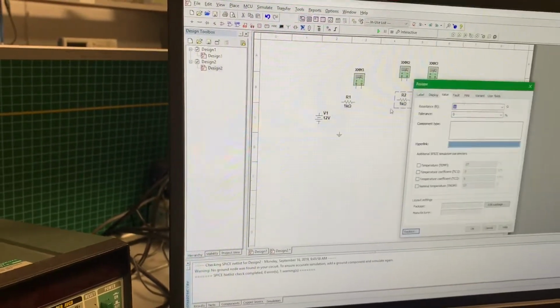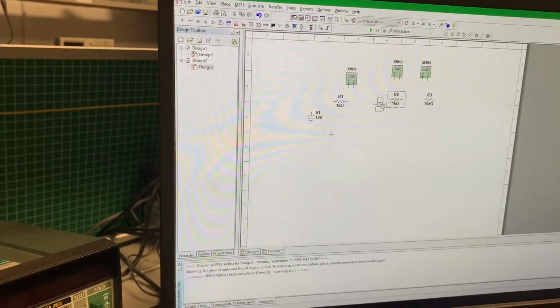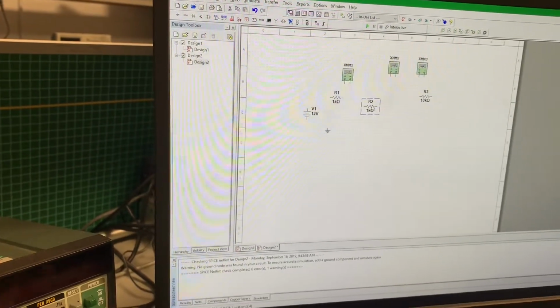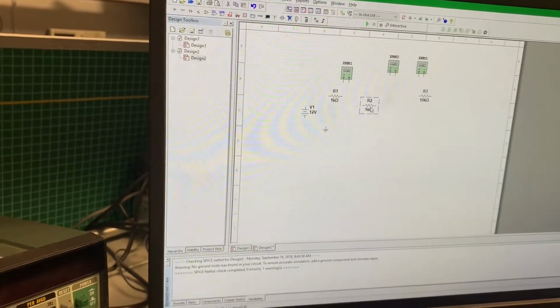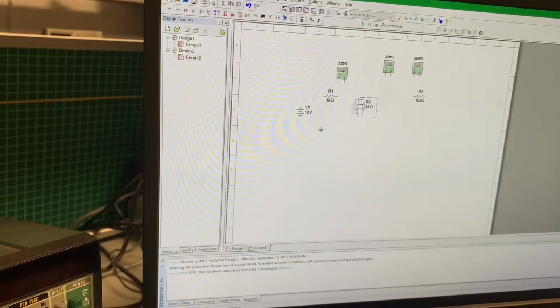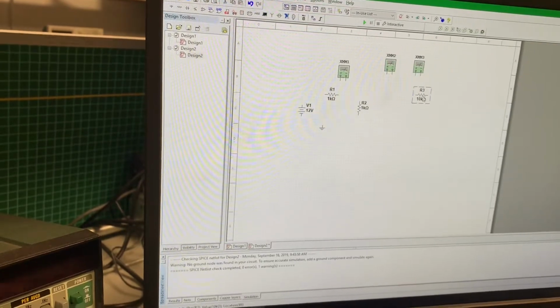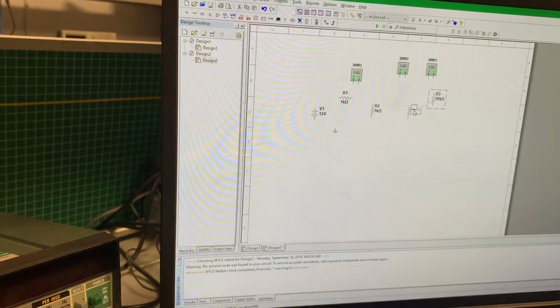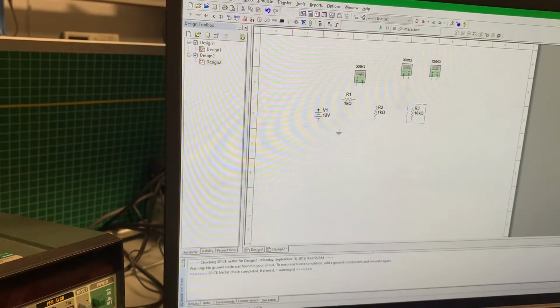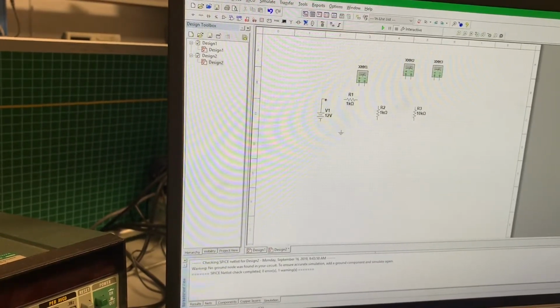Alright, so now we'll build the circuit, and this is actually shown to you in figure 1 on your lab. And to change the direction of the resistor, you can do Control R, and it'll flip the resistor up and down, left and right, however you need it to build your circuit. And you saw earlier that you can pull wires from each component to the next.